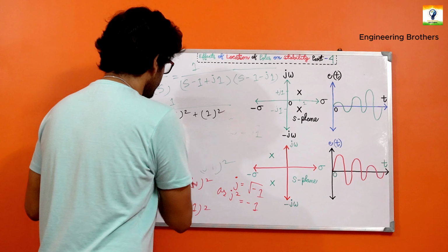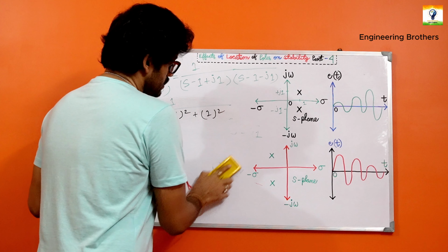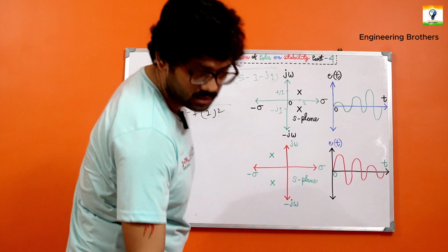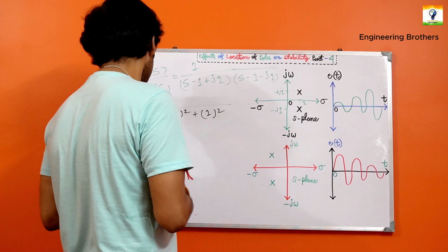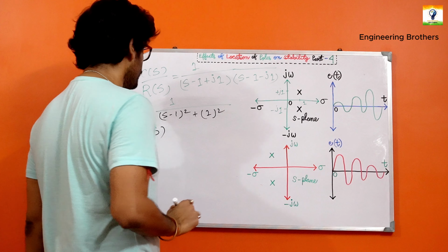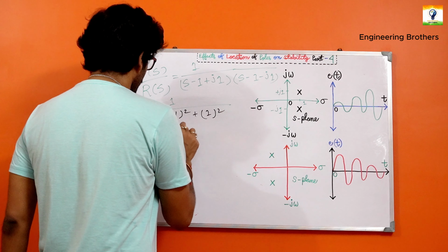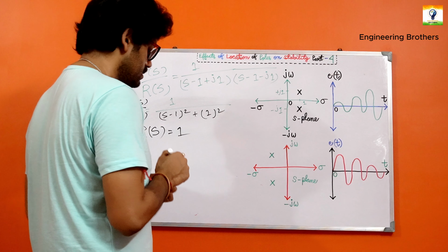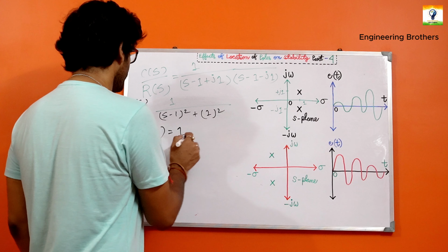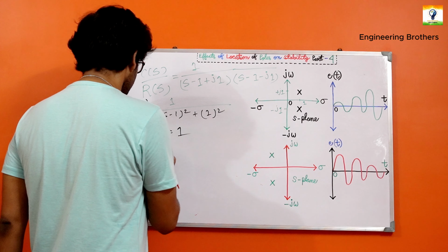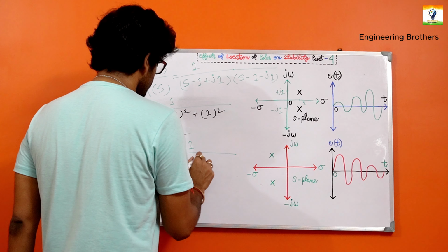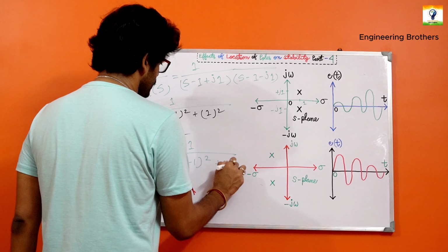For our present consideration, if you consider the impulse response, we can say that the input in this case will be R(s), and as we are taking the impulse response, R(s) will be 1. Quite naturally, because of this impulse nature of our considered equation, we have C(s) equal to 1 divided by s minus 1 squared plus 1 squared.